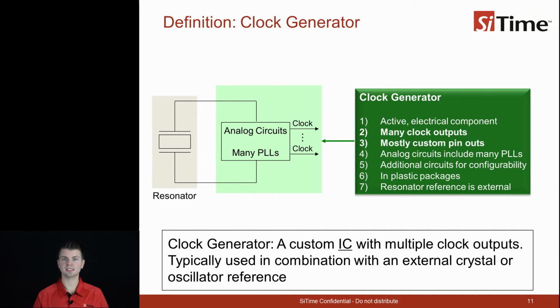They are often used as the central clock resource for a system and supply most if not all of the clock needs of the system. In most cases, the pinouts are non-standard, with the exception of the Intel-defined clocks used in servers using Intel chipsets and for some gaming platforms. Using one clock generator for an entire system can present system design challenges.